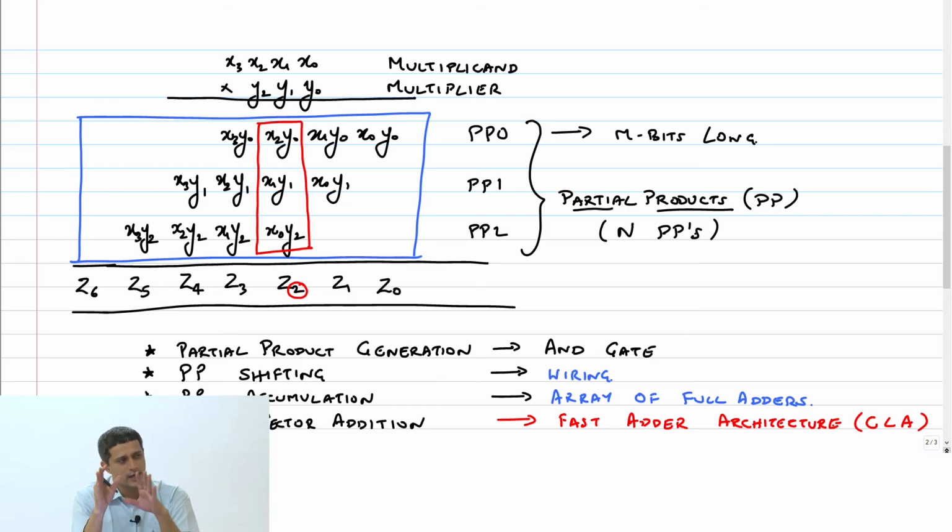Actually in reality, if you look at a microprocessor, nobody cares if you are doing 4-bit into 3-bit. Everything will be converted into 4-bit into 4-bit. You append zeros and proceed. Right? That's all. So this N and M is only to tell you which one is giving rise to more partial products, that kind of thing.